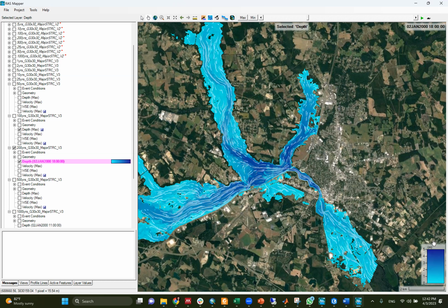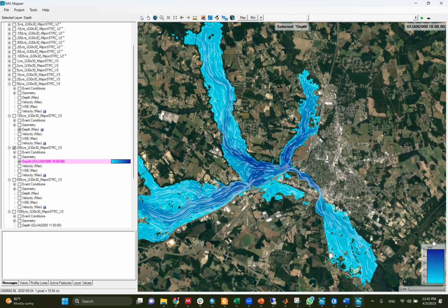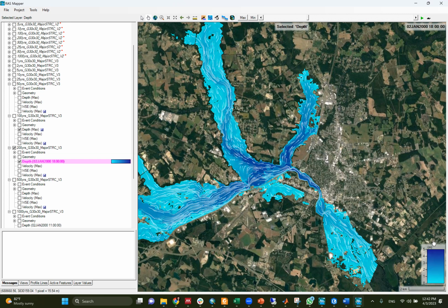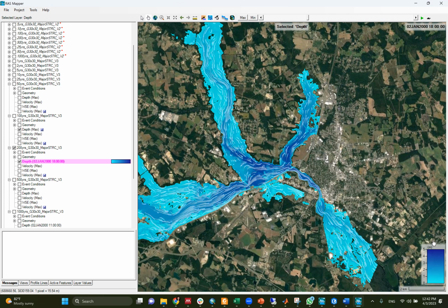And I will not let you develop an algorithm to identify an archetype. So I will also tell you what is the archetype of each building. Is it archetype 1, 2, 3, 4, 5? And then we will develop a MATLAB code that assigns a fragility corresponding to each archetype. So in the for loop, we'll make a condition like if this is archetype 1, use these fragility parameters. If this is archetype 2, use these fragility parameters.